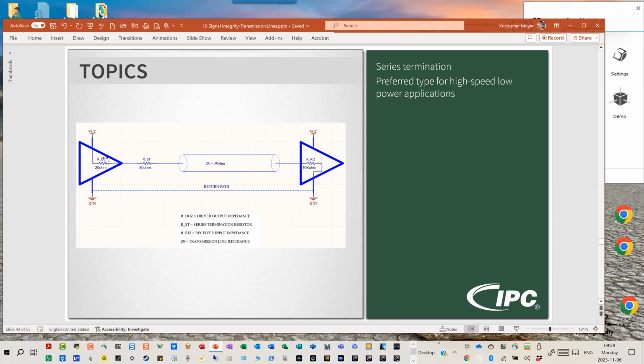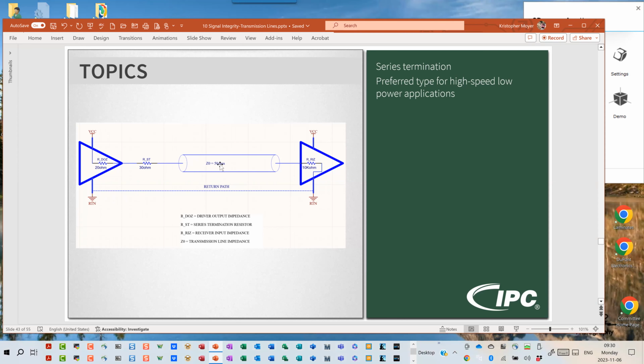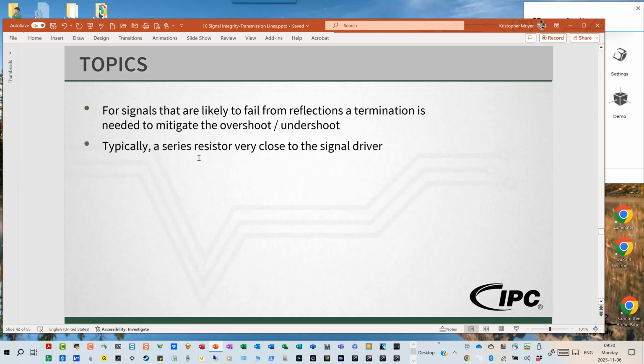Now, because there is no set standard that dictates to the silicon guys that you must make your output impedance exactly 25 ohms, right? Due to the nature of how silicon is designed, and the geometries and the process variation, we have some variance in our output impedance. So one manufacturer might have designed their silicon with an output impedance of 20 ohms, the next might be 33, one might be 19, and whatever. So all we need to do is determine from the data sheet what the output impedance of the driver is, know the impedance of our transmission line, and we simply select a series termination such that the combination of our series termination plus our output impedance should equal this. Then we get back from Electronics 1 what we call the max power transfer, where we want to set the combination of this impedance plus this impedance equal to each other. And that way we can go back up here to this equation right here.